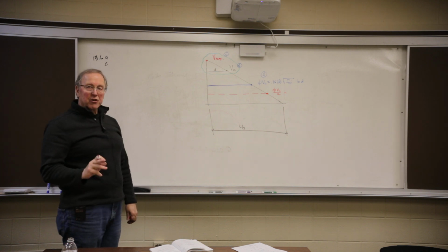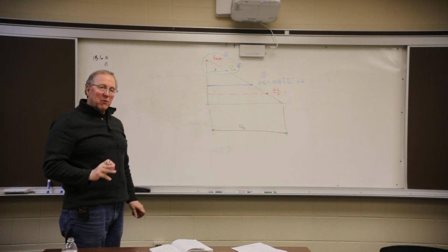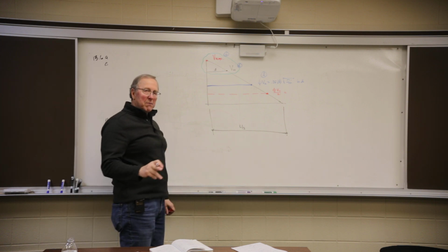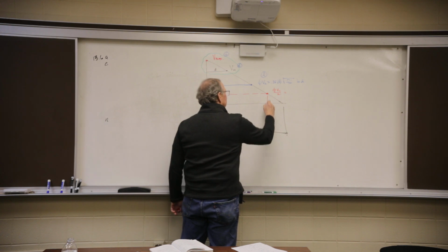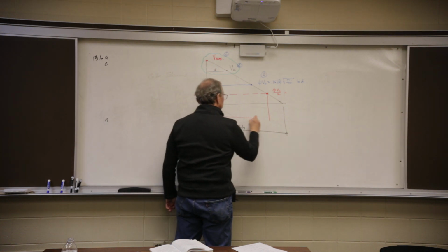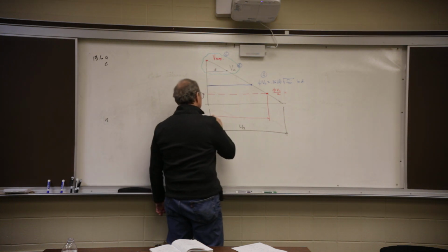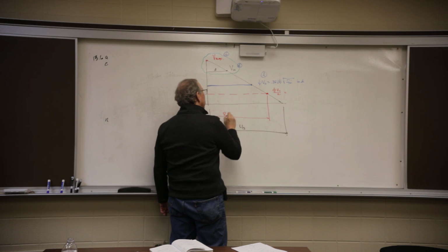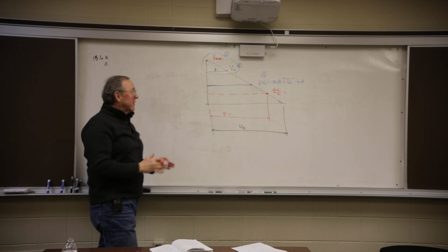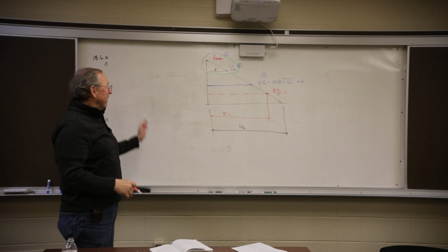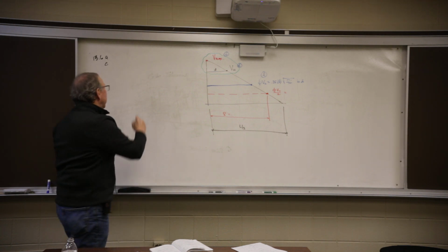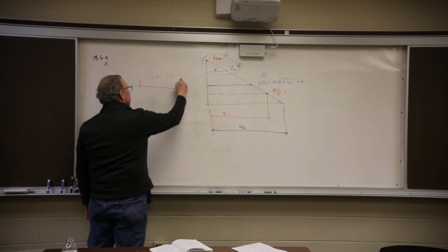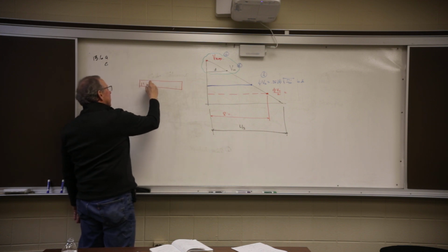Okay, this is one of the critical points. We need to figure out where the stirrups go. Here's the value right here, letter R. Letter R is where the stirrups have to extend to. So from the left end over R, the right end over R, we're going to have stirrups. So here's my beam. Here's my stirrups.